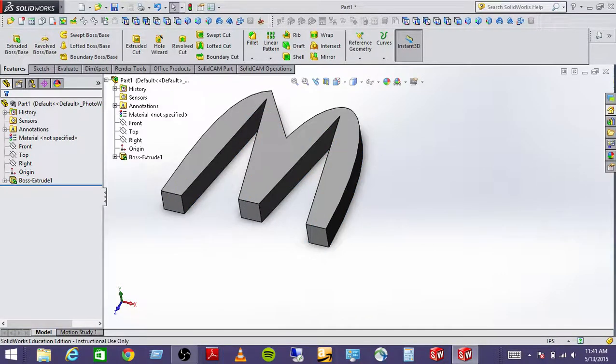You have any questions on that? Or a third thing you could do is understand that it's a nominal size. It's probably going to be in plastic. It's usually under, so a 1/4 inch piece might come in 0.238 instead of 0.25, and you can design your part to be well under that so that you have to machine that part.